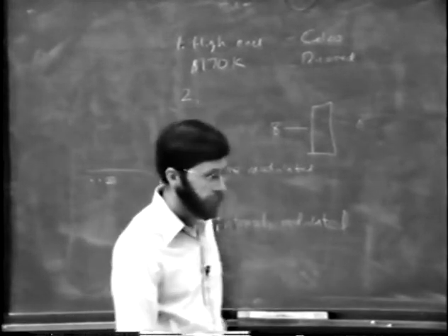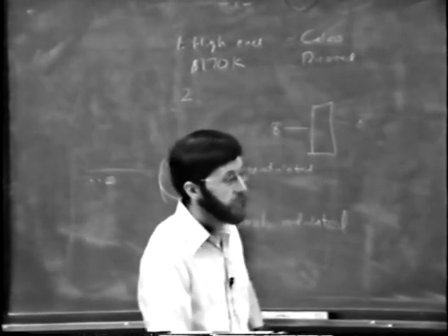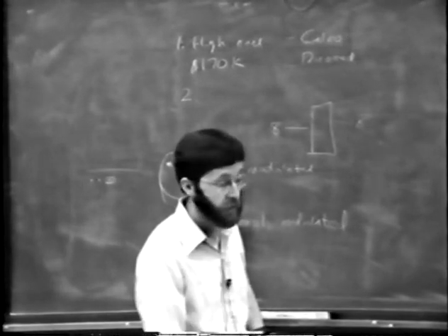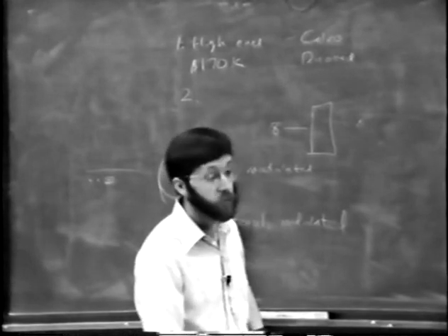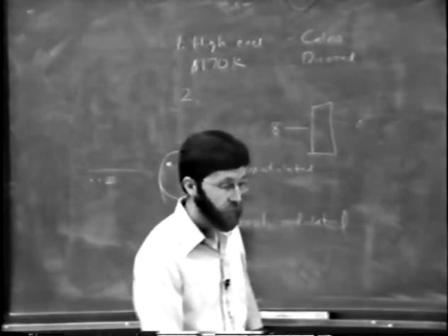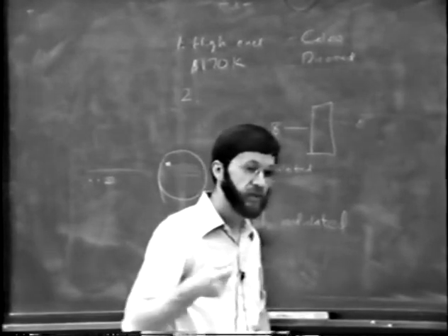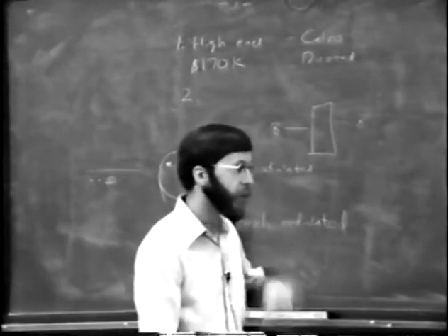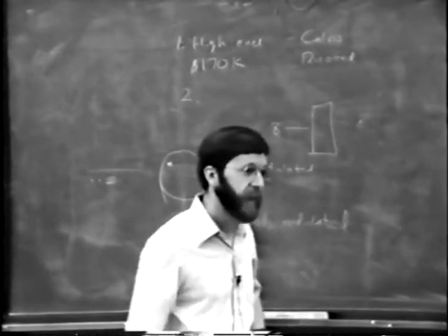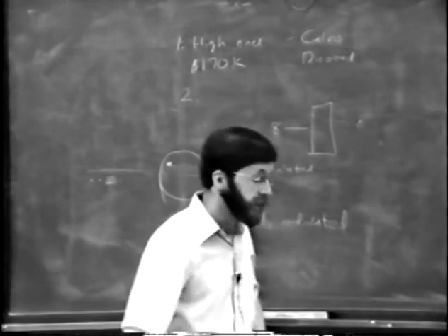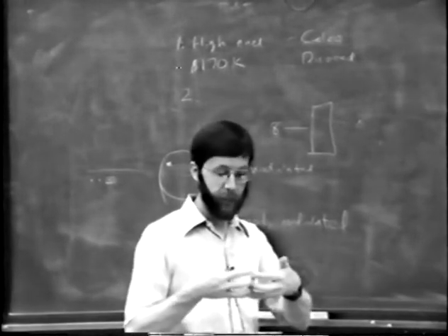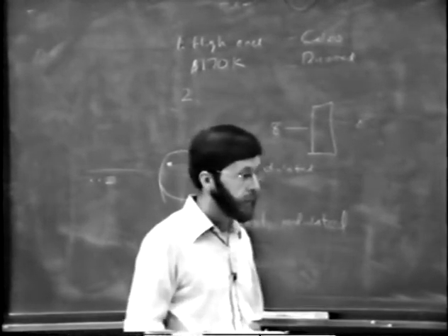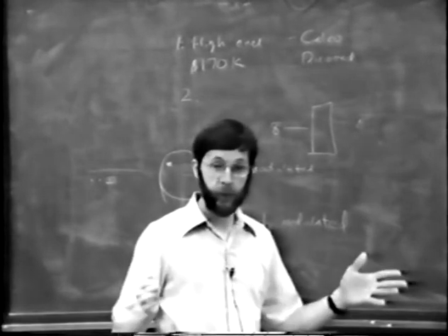Well, they were very skeptical. The first story was that the focus circuit comes from the manufacturer and it was not changeable. And that wasn't true. And finally they said, well, we'll put in a knob for adjusting the focus, but it will void your warranty on that. He says, okay, do it. We want it. So they gave us a focus knob, and we defocused the beam so that the dots overlapped on the screen, and then ran it and jacked the intensity way up, and made beautiful looking pictures, which we showed them.